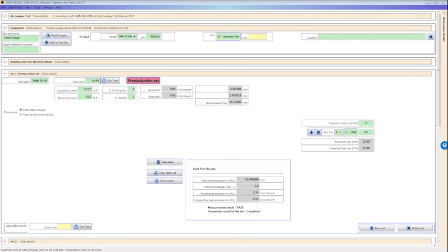I think one of the reasons engineers think they want to go up to the actual operating pressure or the maximum pressure of the duct is they want to see if the duct's going to actually hold together. So it's not so much whether it leaks, it's whether the thing holds together. I think there's an assumption that when you put pressure on it, somehow the duct will kind of pry itself open. It's not actually something that I've ever seen, but I guess it's theoretically possible.